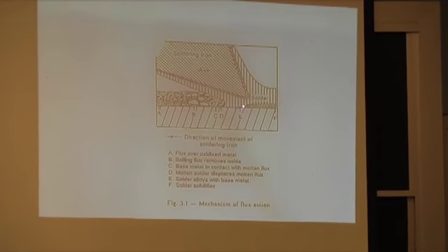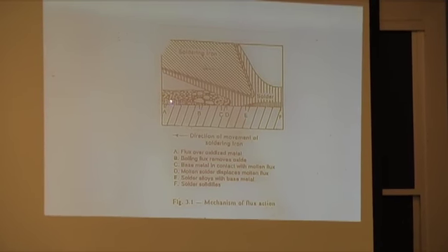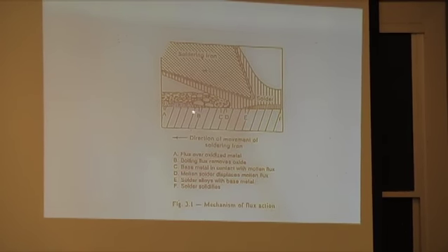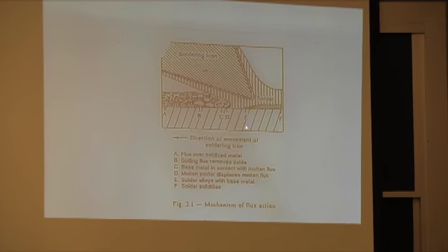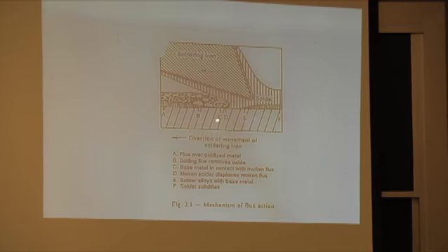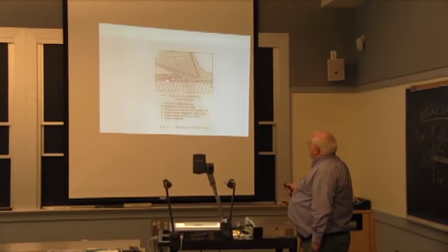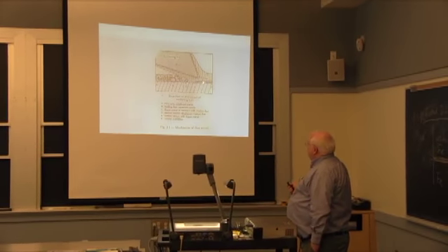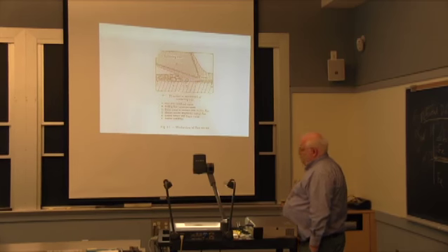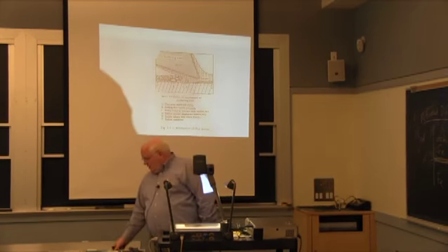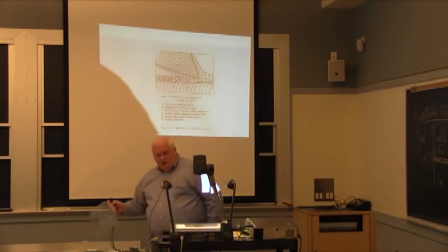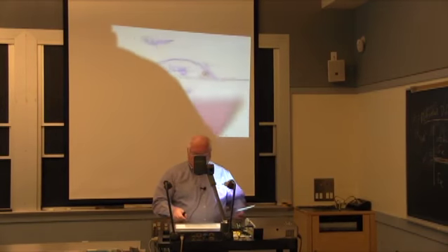You have molten solder, you have solid solder, you have a flux, you have a contaminated surface, which is a little different down here, and you have your base material that you want to solder to. And you have temperature gradients all through here. So it turns out soldering is a fairly complex process, and it's controlled by the inherent wettability of the flux, the solder, the base material, and the solid solder and the liquid solder. And that, as many of you know, is governed by Young's equation.